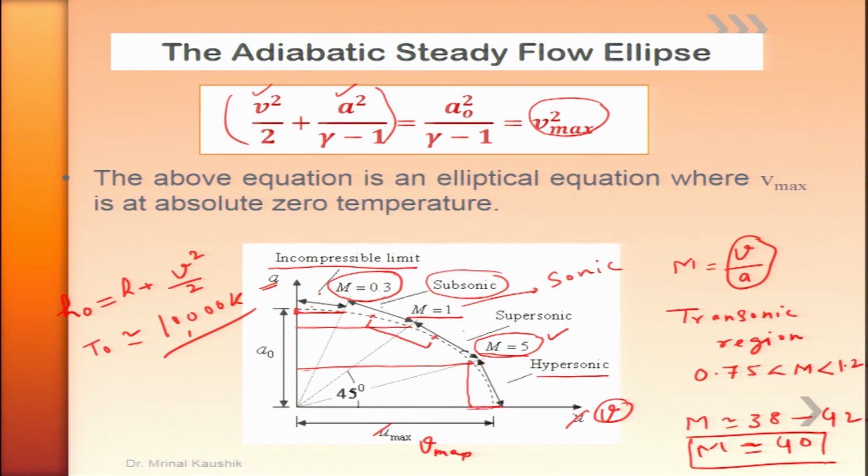Beyond this temperature range, as we said, the nitrogen completely dissociates, because we have seen in the perfect gas discussion that around 9,000 K the perfect gas assumption, which is approximately true, no longer holds, because when we take the dissociation effect of these molecules into account, then at something around 9,200 Kelvin the perfect gas assumption does not hold.